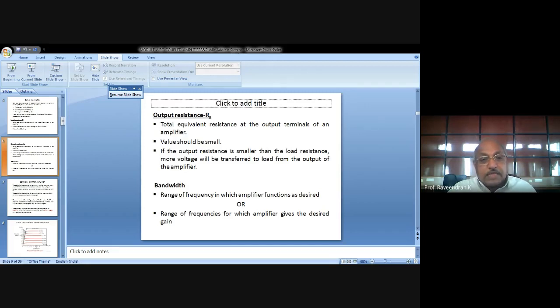Or otherwise, we can say that the new transistor, which is used for replacement of the old one, will make the transistor operate in the earlier manner, very similar to the earlier, maybe with a better output because the beta is somewhat increased here. So with a certain output increase. Okay, so in order to replace the transistor, if the operating point is independent of the transistor gain, then of course you can replace the transistor very easily, because the operating point is independent of beta. And that is the main reason.